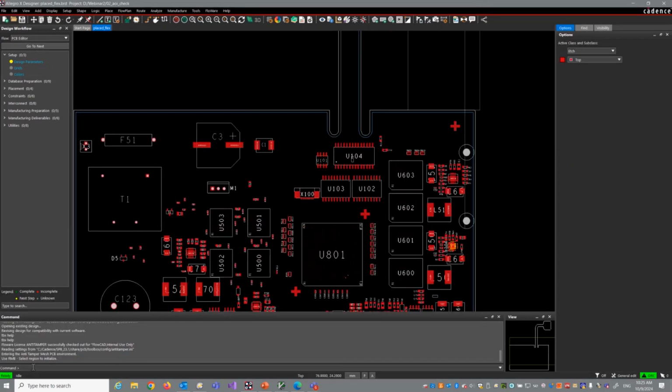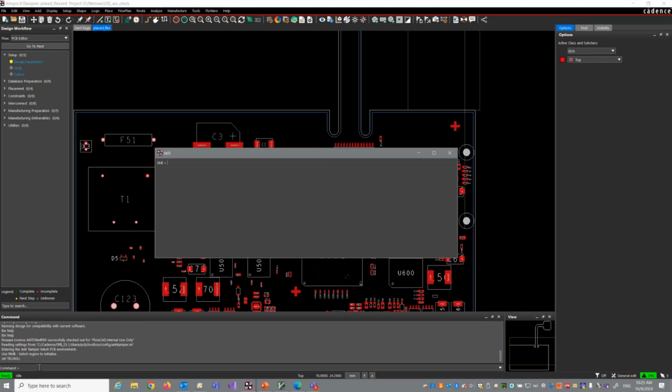So as I mentioned, how do we work with SKILL before I go into the live demonstration of some modules? As I mentioned, set telskill. This is all you have to do. And now you have a SKILL interpreter window, and you can enter your commands. So be curious. So for example, printf. This is like hello world. Hello world. And now the application returns hello world.